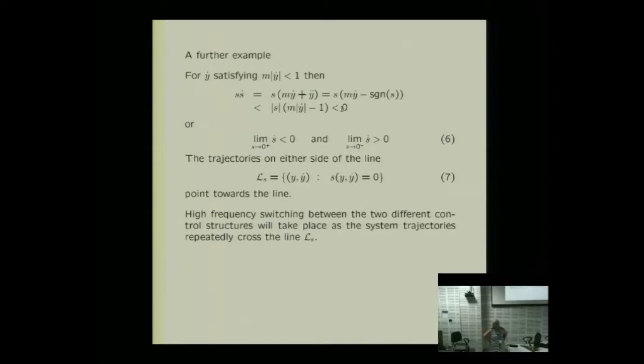And that's the first time I've mentioned high frequency switching. And this has been a big bugbear, really, for sliding mode control, because in theory, we require high frequency switching. Okay? So many of the theoretical properties we will discuss are predicated on high frequency switching.